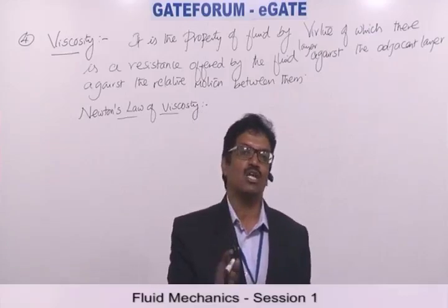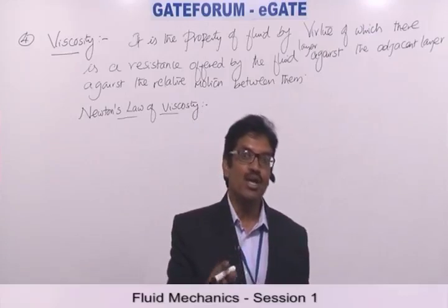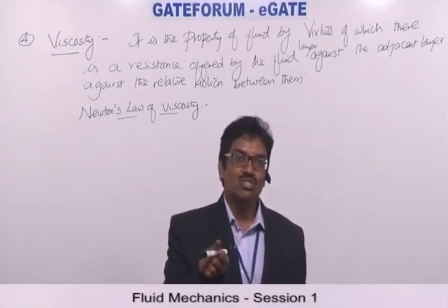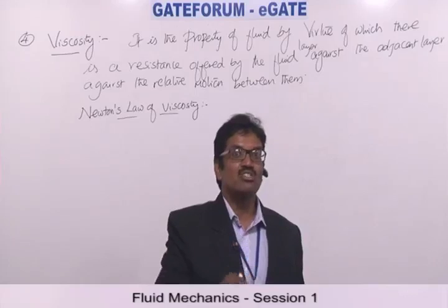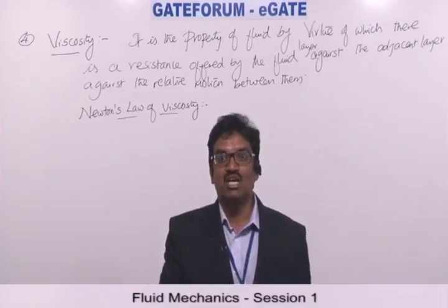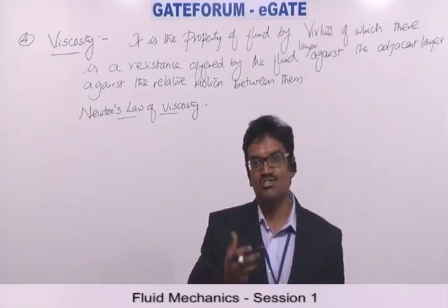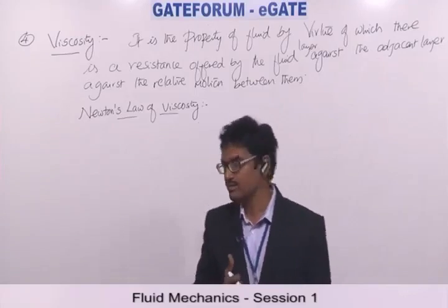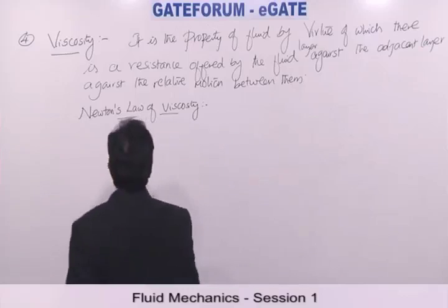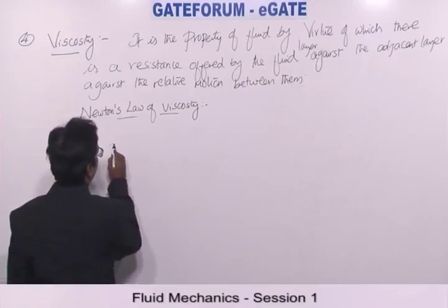Only when it is in motion can you see the influence, the effect of the viscous nature of the fluid, because viscosity manifests itself in the form of the shear stresses between the fluid layers, tangential stresses between the fluid layers. So if we just look at Newton's law of viscosity,